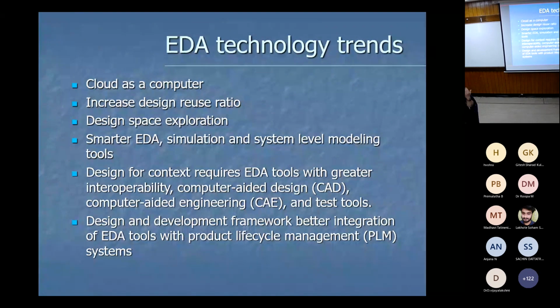But today you need a complete framework, a solution framework, for us to design. As I said, if you're talking about synthesis, it should look at all the RTL related issues and give you a better netlist. And it also has to consider the physical design issues or challenges, like, will it cause congestion?